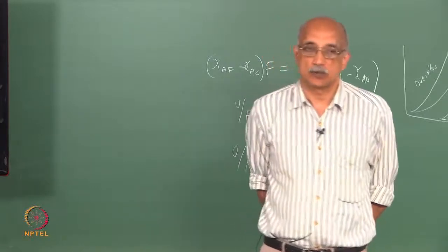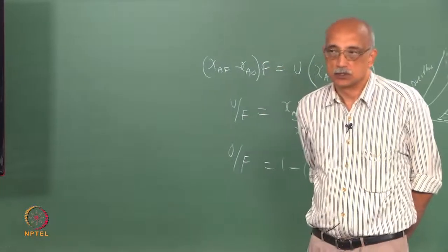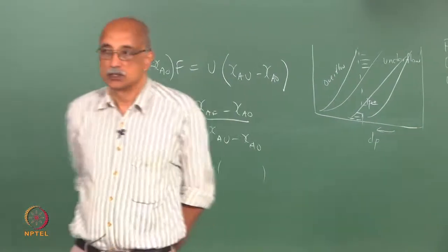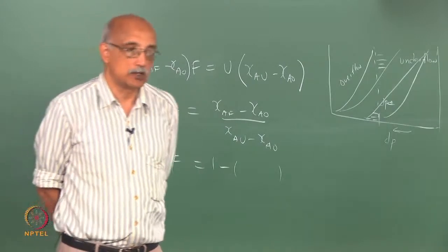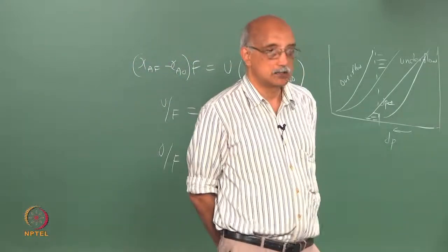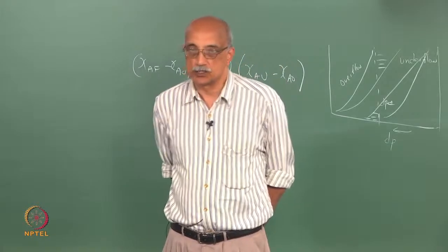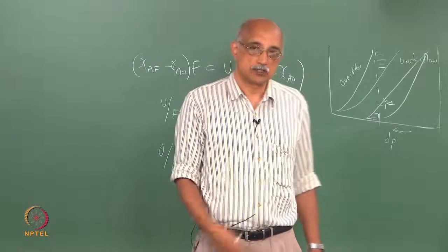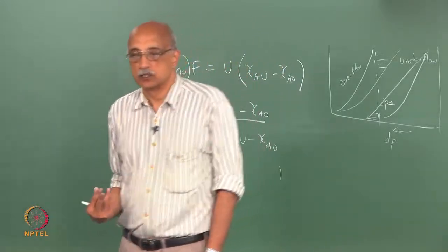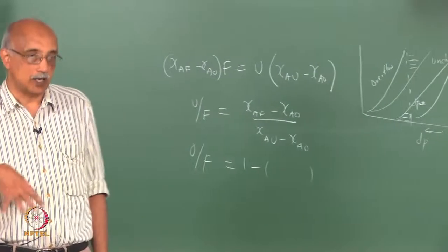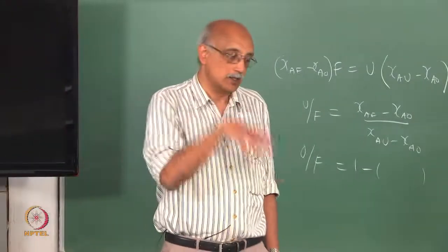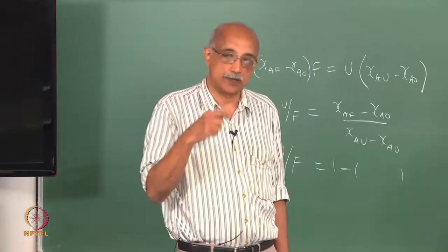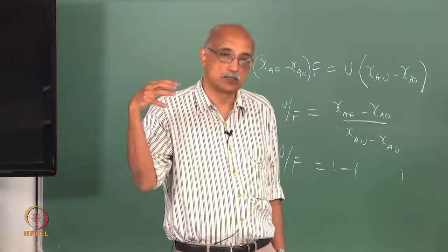But what is going to happen if you keep increasing your feed amount? Some of these problems that we talked about earlier, agglomeration will become worse. Interference of one particle approaching the screen by the next particle can become worse. Blinding can happen. Eventually, you may even start to have damage of the screen. If you have particles that are approaching at some velocity and you have a large number of them impacting in a certain location, you can actually start to create small holes and other pathways that particles can escape through.